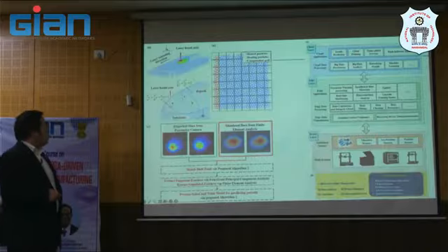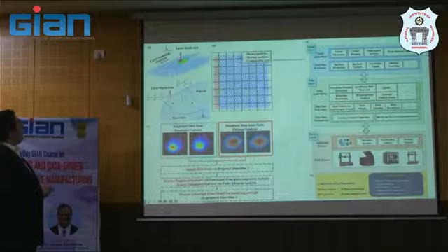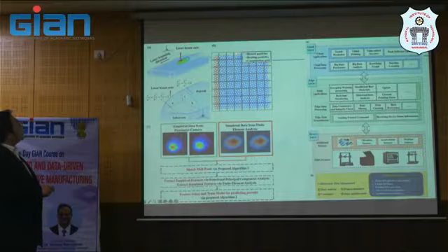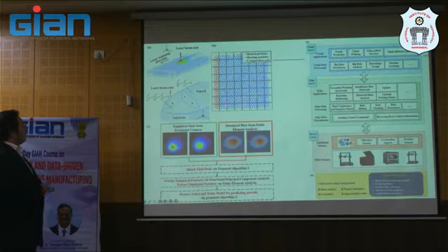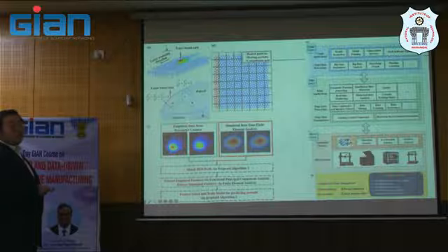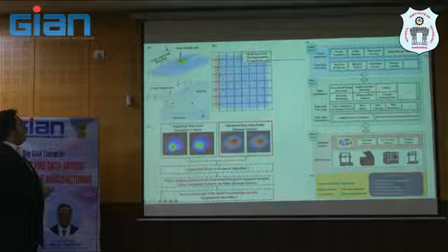And that actually has a more specific example in this kind of finite element calculation here. And then you use some powder properties, some way, somehow you treat it in your computational grid. Here, there's some material actually heating, some material already heated. And then you will try to predict something that you can use a pyrometer camera to detect the melt pool size, and then to compare again with the simulated data from finite element analysis.